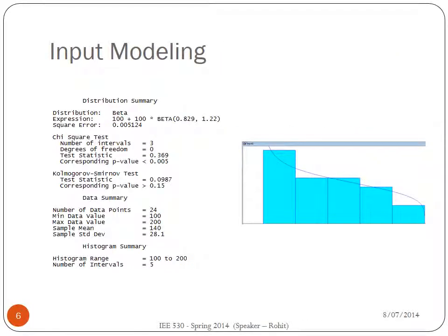When we were given the data for the case, we looked at the input data which was given to us for a 24-hour time frame from one of their pilot runs, and each hour there was a number of entities that arrived. And so what we did is we took that data and we did distribution on it, and using Arena we did some input analysis, and the 2 closest distributions were an exponential and a beta distribution. And in the end the beta distribution won out because it had the best chi-square test value. And so that's what we use for our arriving entities.